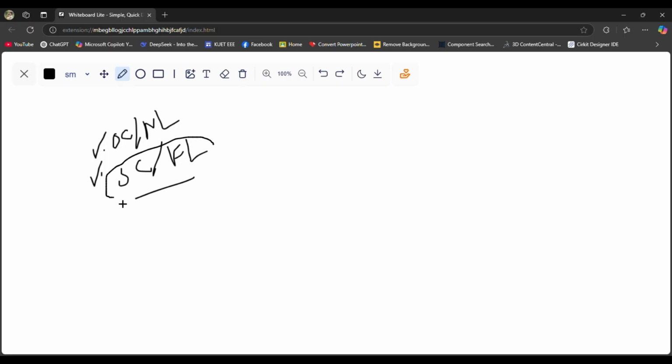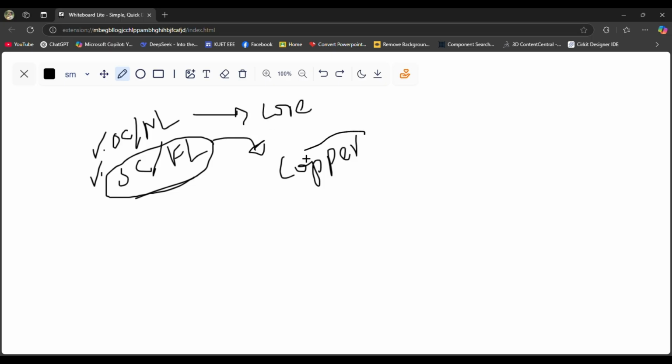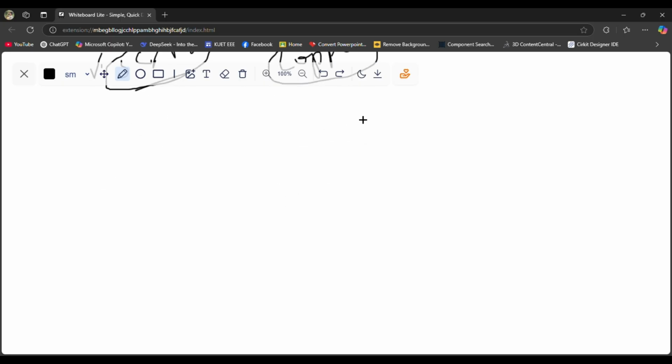We are doing this short circuit test, or full load test, in this experiment because we want to find the copper loss component. We do the open circuit test, or no load test, for the core loss component, but to get the copper loss component we have to do this short circuit test. So if I draw the circuit diagram, then it should be like this: